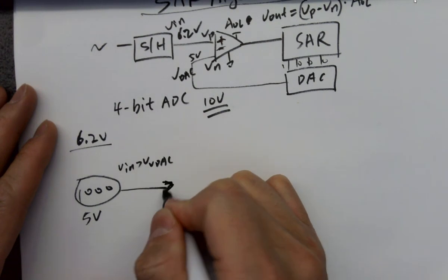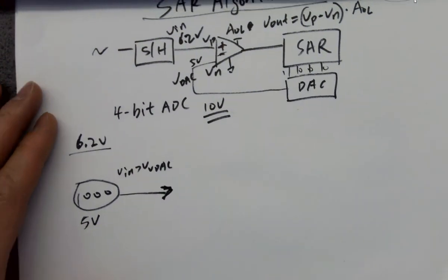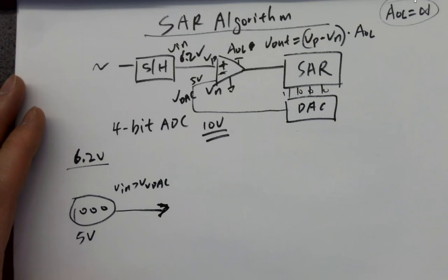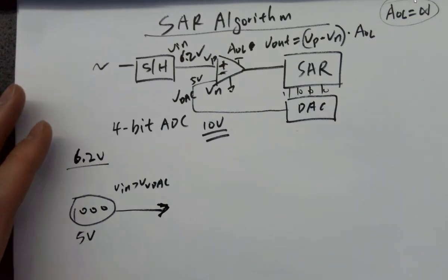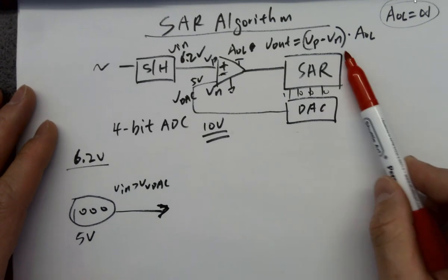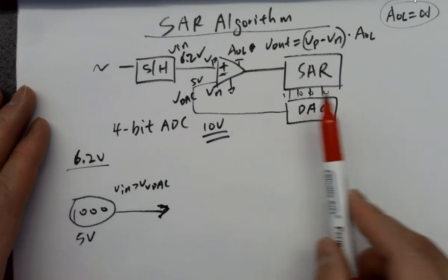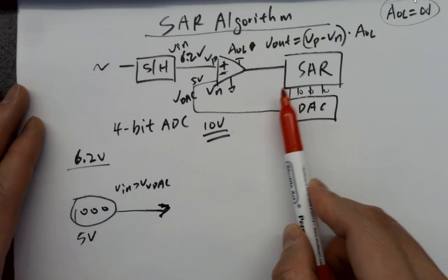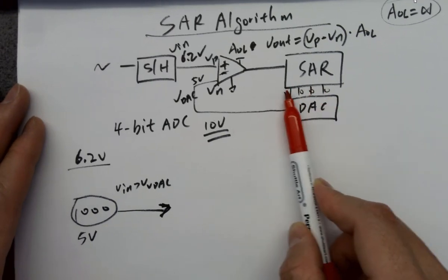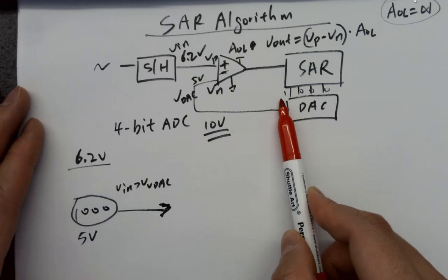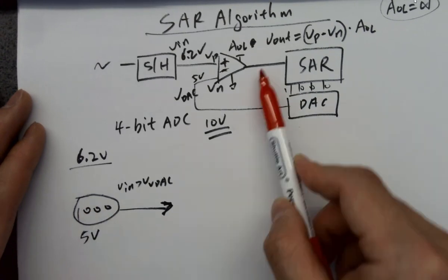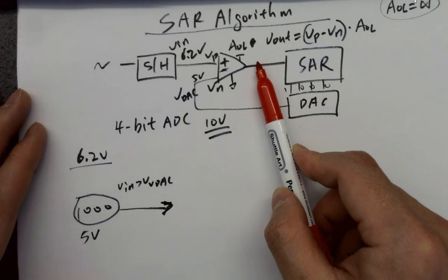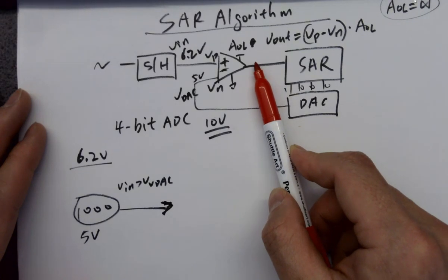What this block is going to do is shift all the existing codes to the right by 1 bit, including this little one here, and plug in that. Let's call it A3, since you eventually are having 4 comparator outputs.